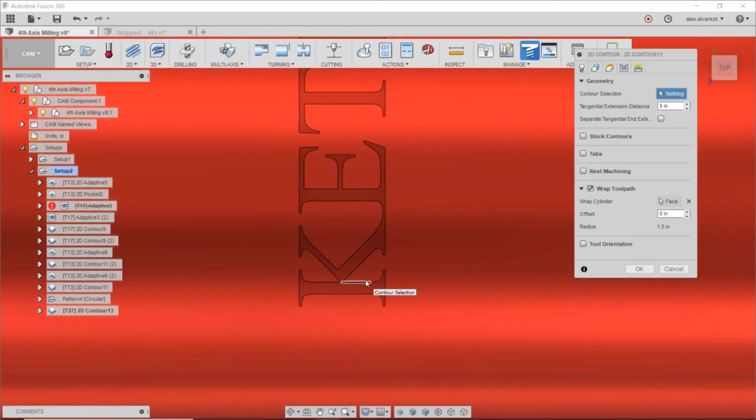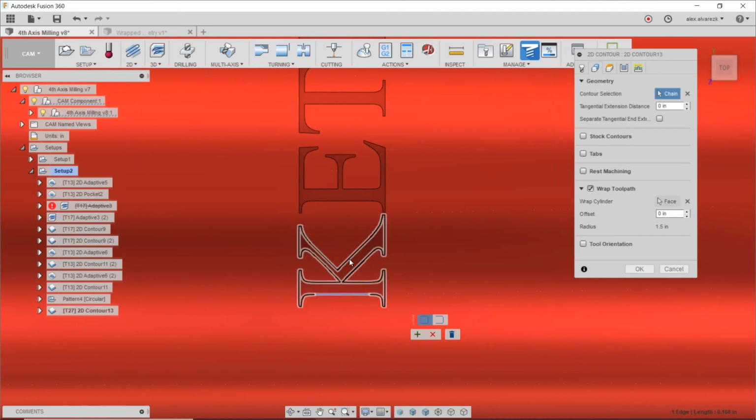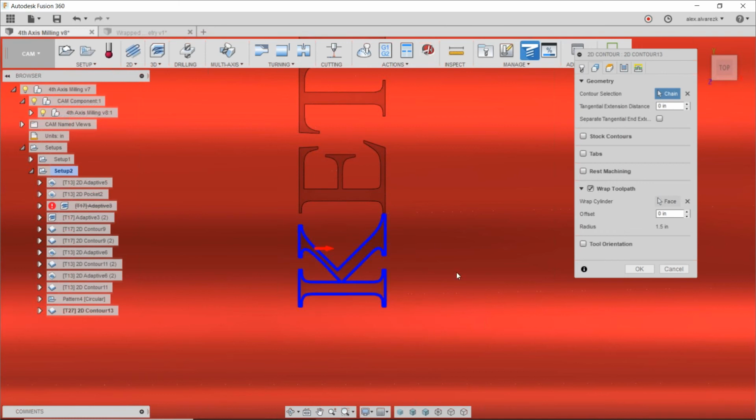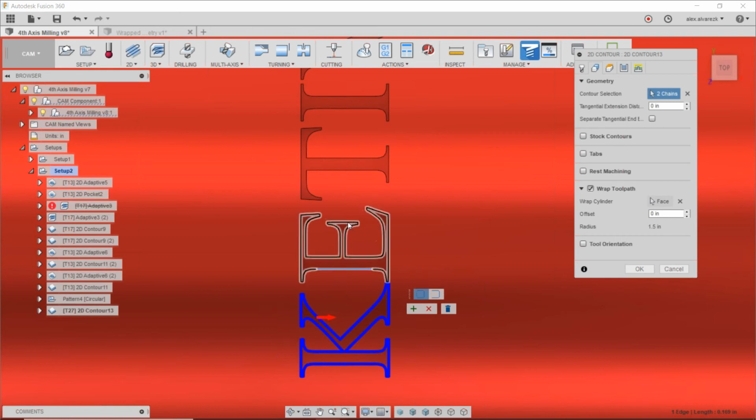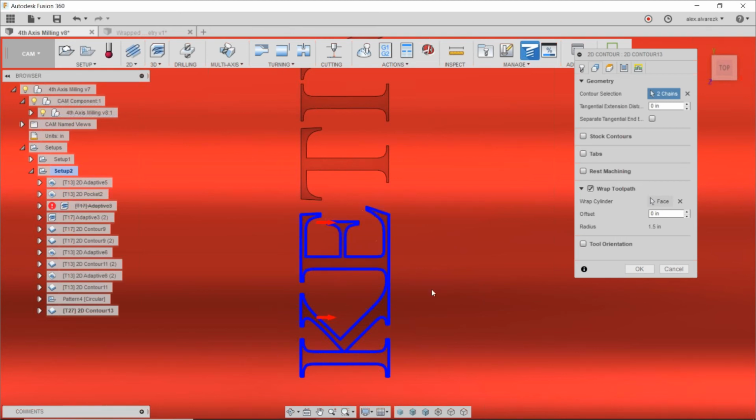Notice how it begins selecting some of this individually, right? So you can go ahead and select this, and it only selects that edge there, right? So what you can do then is just click on that edge again. Notice that it's open contour. Go ahead and change that to a closed contour, and hover over some of these edges until you get that entire closed loop, right? Click OK, and doing that again one more time. And then just selecting until it closes, right?